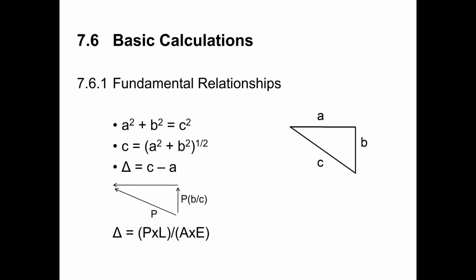But the reason we tension from both ends in some instances is because we know we've had some force lost between those ends. And so it is the same force that's applied at both locations, and it is the full tensioning force that's required for the strand.